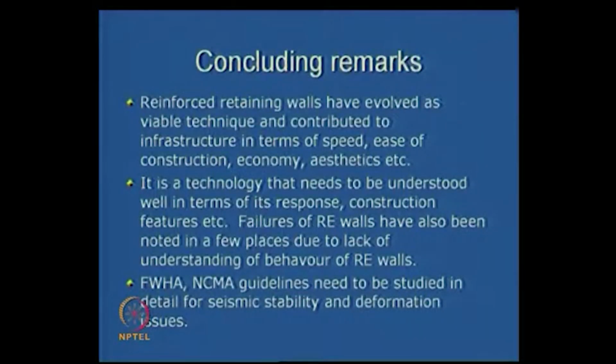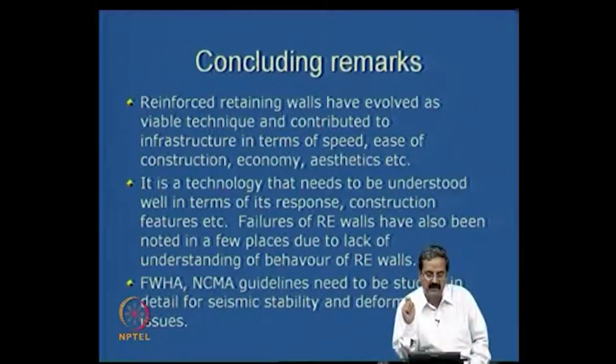So what I want to say is that the reinforced soil technique is very viable, and has been a very useful technique in many countries, and it has contributed significantly to infrastructure. It increases the speed of construction. It is very useful to construct. The speed of construction is very fast. Of course, it's economical, and aesthetically it's wonderful. Compared to many of the treatments for retaining walls, using precast panels or segmental wall construction, you can bring in a lot of nice finishes to the retaining structures.